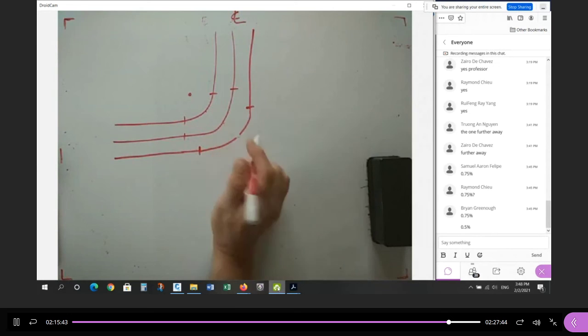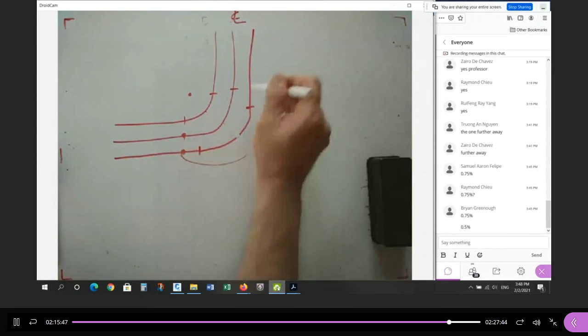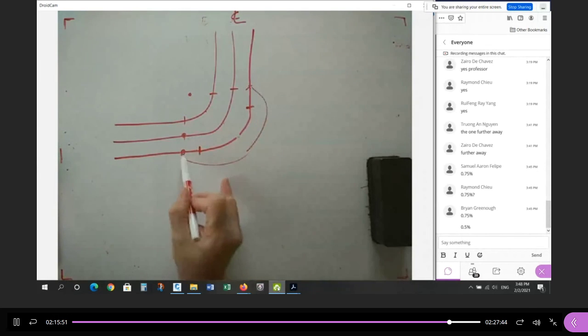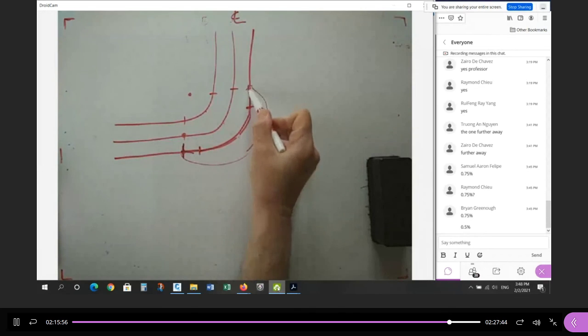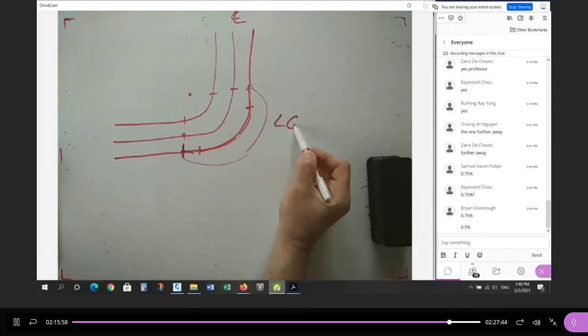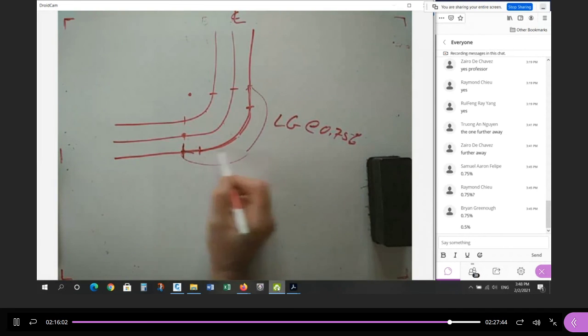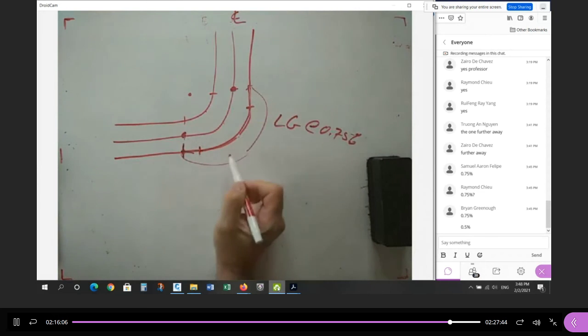Okay? So what's unusual? Well, from this point all the way around to this point. That's the length of the gutter. The length of the gutter from here, straight line, curve, straight line. That's the length of the gutter at 0.75% gives you the rise. The rise is the same between these 2 points.